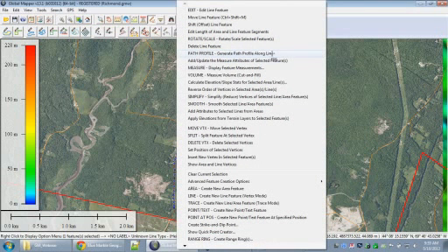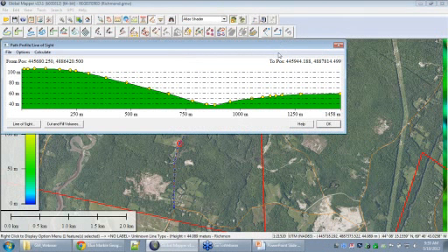We can right-click on that segment of road, and we can do a very quick path profile on that. So this will give us an elevation profile along that stretch of road. In this case, the road layer itself is only a 2D layer, but because we're filling in the terrain model underneath it, it gives us a very easy means of establishing a path profile for that. So the path profile allows us to see exactly where the elevations are on that. These can be stored as images that you can superimpose on a print map if you're creating one of those.